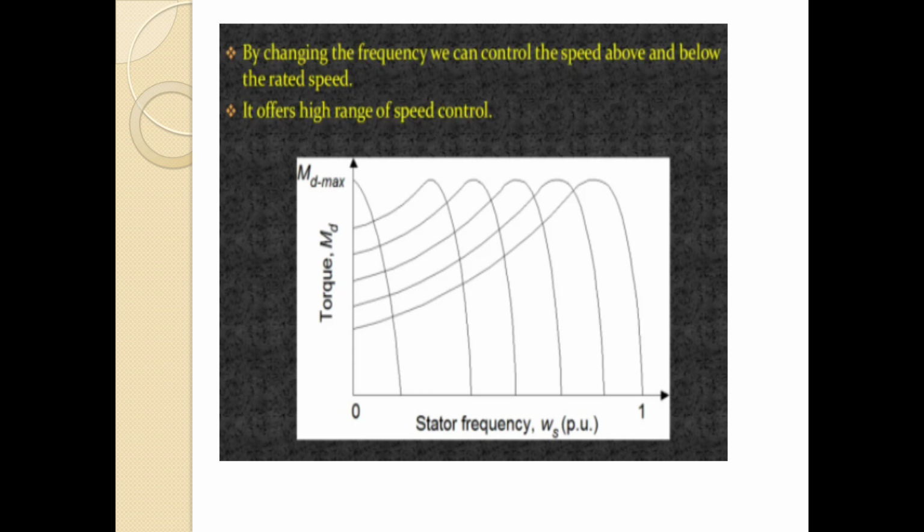Low frequency operation at constant voltage. When supply frequency decreases at constant voltage, the air gap flux increases. Low frequency operation has the following effects: the reactance will be low, more losses, very low efficiency. High frequency operation at constant voltage. V constant, frequency increases and flux decreases. By increasing the supply frequency of the motor, the no load speed increases, maximum torque decreases, and starting torque is reduced.